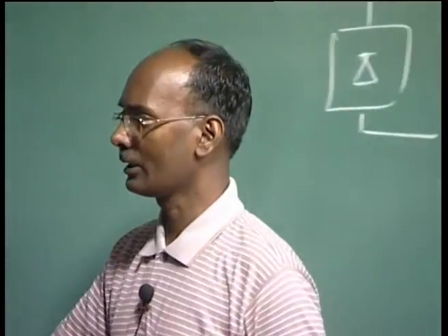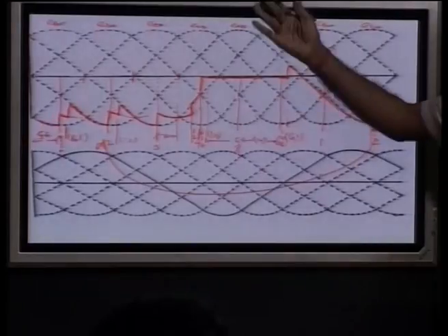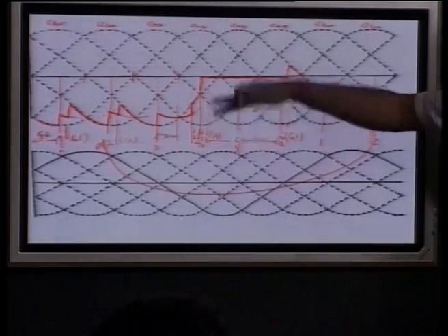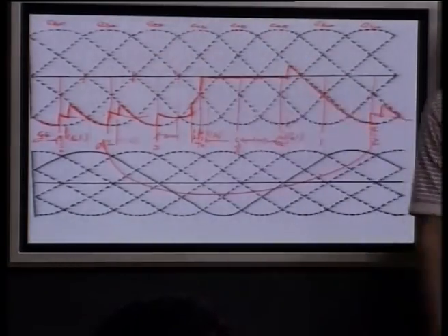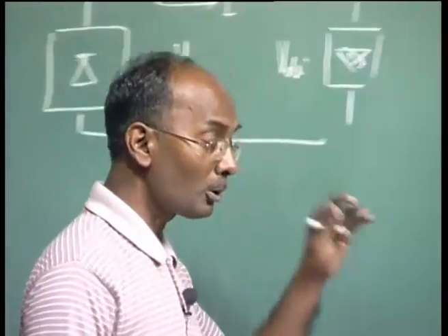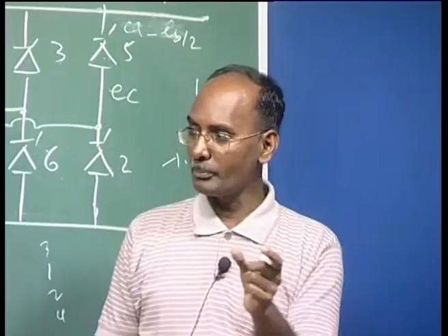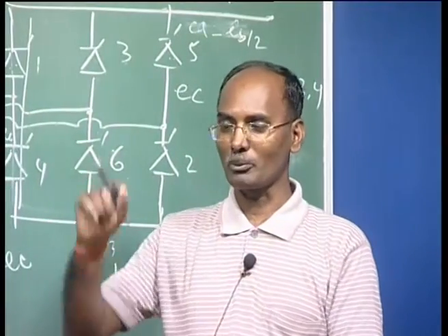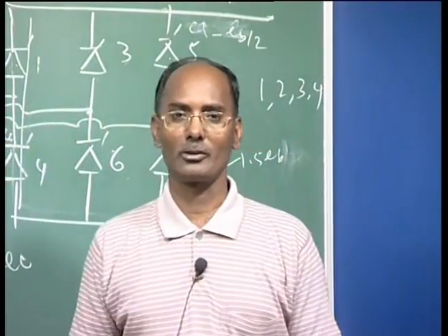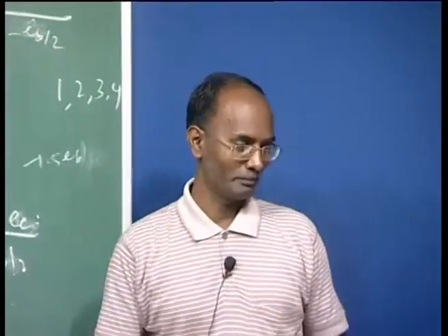You can draw similarly, this is a DC output voltage, and if it is asked what your valve voltage is, it will be coming somewhere on this plane, and then you can draw. The procedure is the same: you should be very careful, find the voltage in this commutation period as well as the non-commutation period, and then trace the figure.